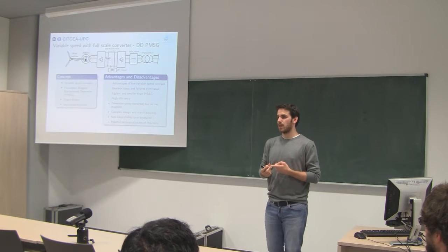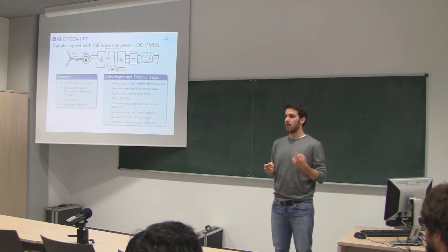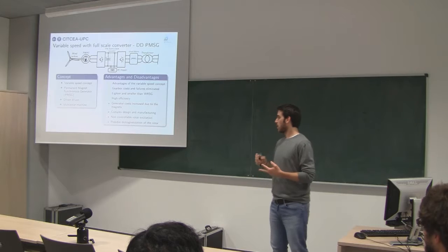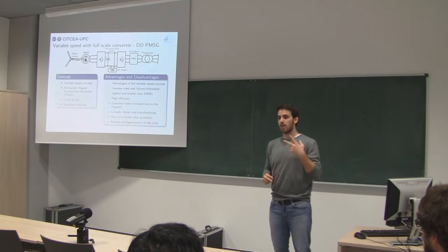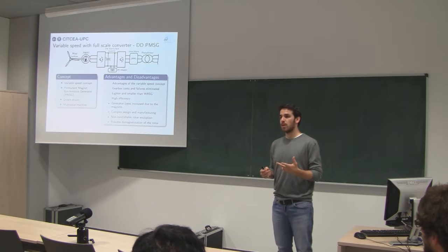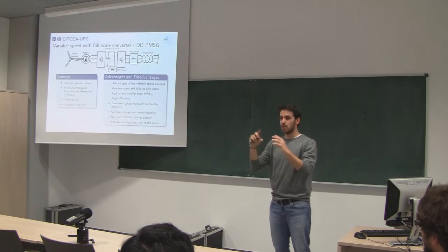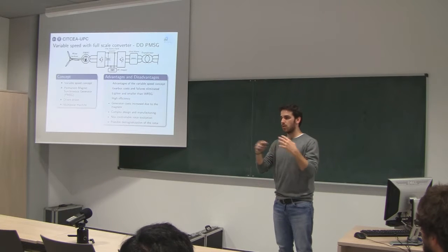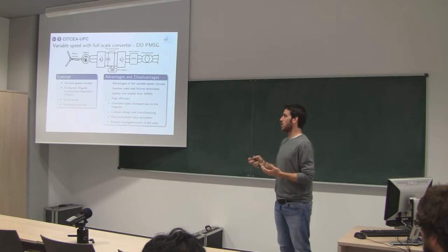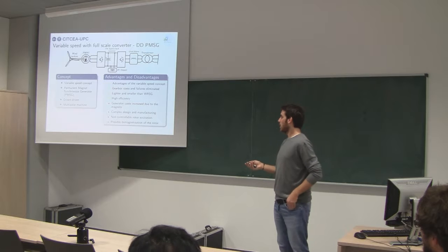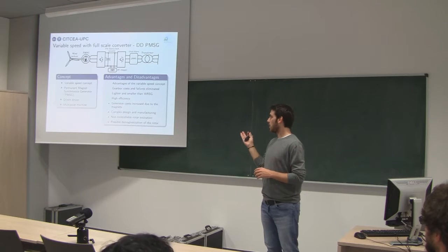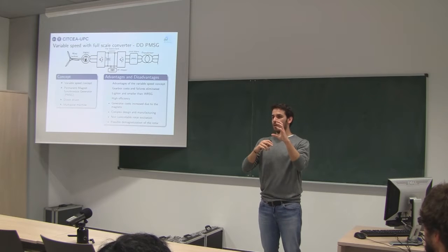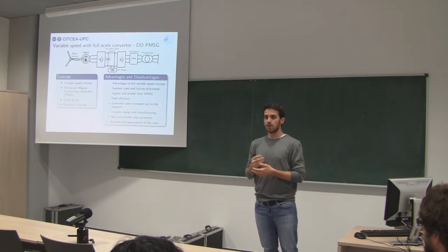The first one is that it's a bit expensive to buy. I think that the magnets are neodymium ones, so this is not cheap, of course. Then you don't have any possible control of the rotor excitation, because you have a permanent magnet there. It's not possible to do anything with the rotor magnets. You have a constant flux there, so you cannot really reduce or increase the voltage. So you don't have any control capability on the generator, and you can only control with the machine side converter. And potentially, if you have a short circuit in one phase, the large current flowing through the coils of the stator could demagnetize one of the magnets, and then this could cause a failure in the system.